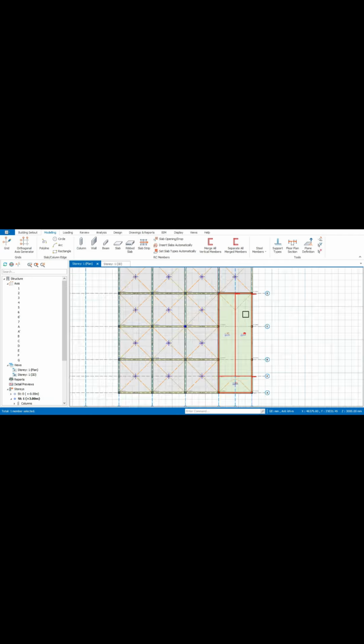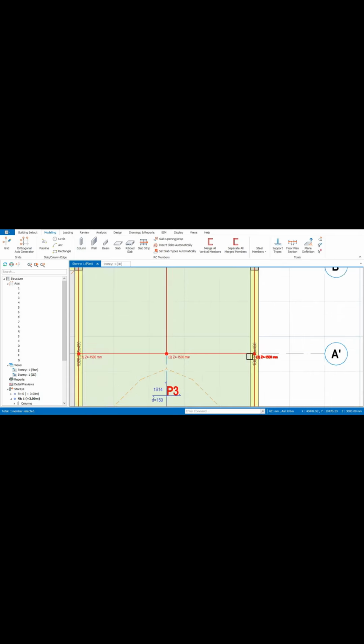So let's go to 3D to check again, and you can see that it's now properly done. The first points that you are bringing down are supposed to be your 1 and 2, while the secondary point that you are leaving at a different height up is supposed to be just your 3 and then your 0.4. But usually, because you only have the luxury of editing 1, 2, 3, you need to designate the first 2 points for the part that you are bringing down.